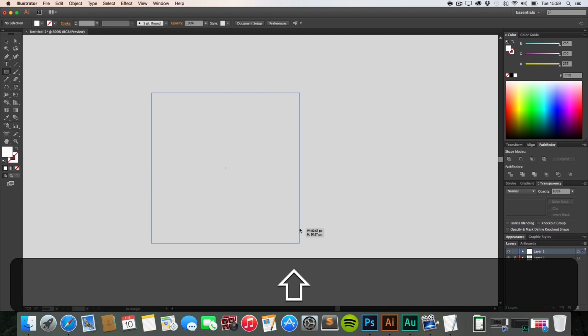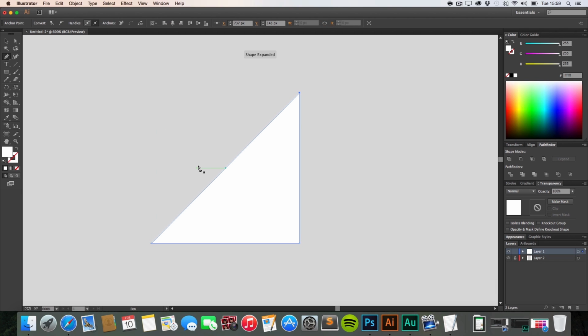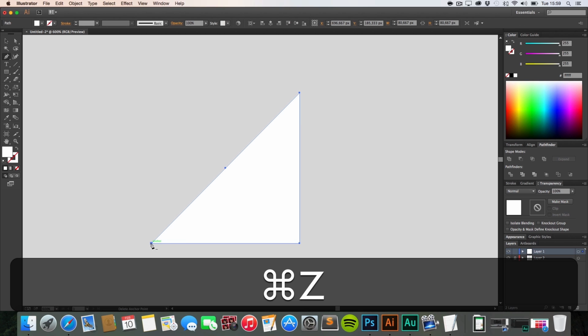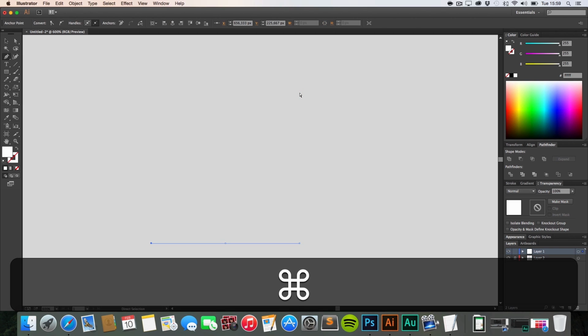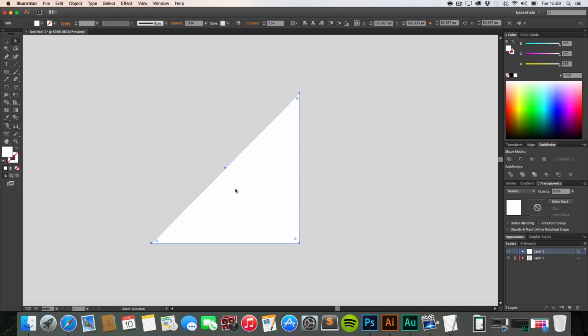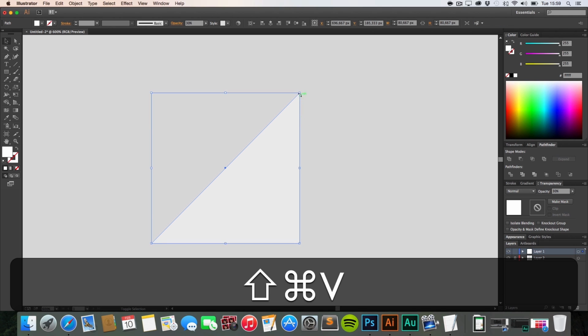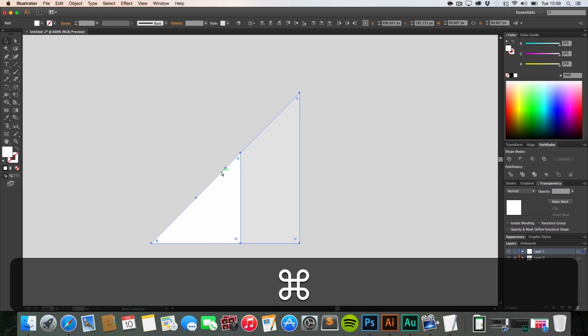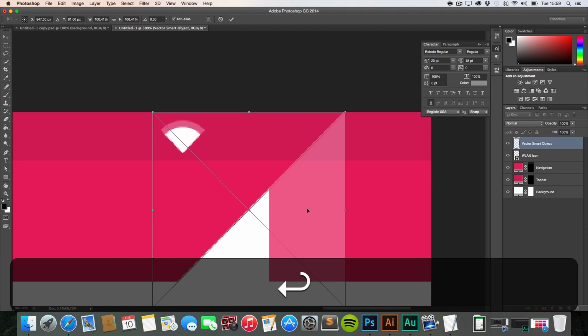That's the basic same approach. We're going to use a rectangle, delete the top left anchor point, and now we have this shape. Let's see if we can close this. We're going to click here. Oops, I've deleted it. Yeah, okay, it's already closed then. And bring it down to 30% transparency. Go to Control C, Control F, and hold down Shift while dragging the top left anchor point down. It perfectly constrains its proportions. And now let's crank up the transparency again. There you go, finished. That's it for the 3G icon.